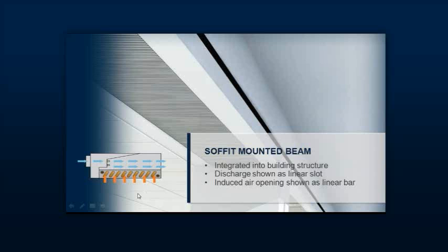The Audi Museum comes to mind. Now, this is a building in Germany that is a very passive system. It uses passive beams. They're installed above the perforated metal ceiling that you see on the left and on the right. Displacement ventilation is used. It wraps the columns and is at low level on the floor. The curved linear that you see on the right-hand side is actually the return for the supply air inside the space. A very calm, quiet, peaceful, well-ventilated space.